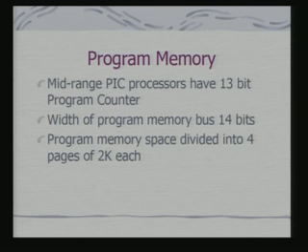Typically, the program memory is 13-bit, with a 13-bit program counter. So, what does 13-bit essentially mean? In fact, it is effectively an 8K program memory. I am talking about mid-range PIC processors. There are other PIC processor ranges which have variants of this size.